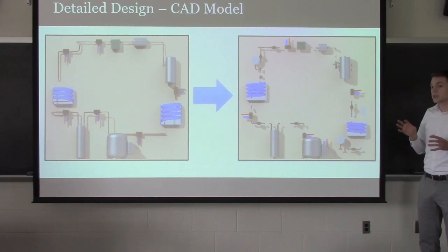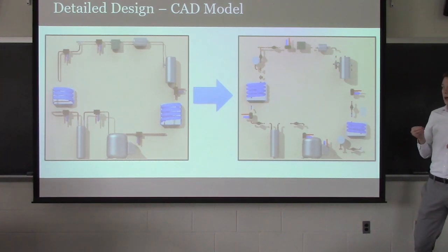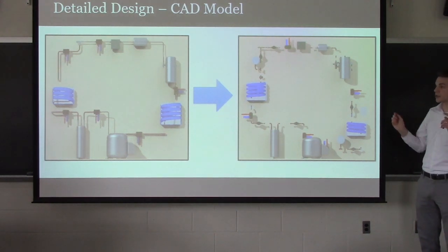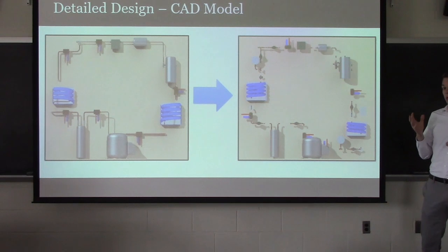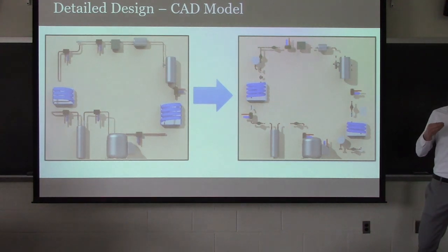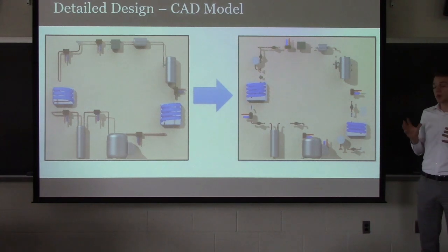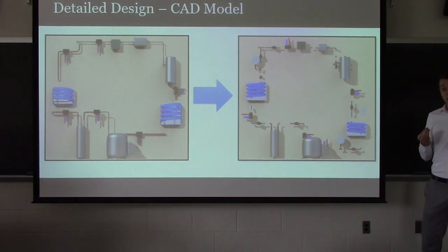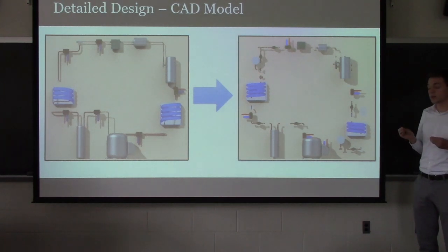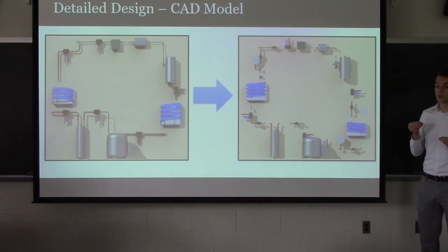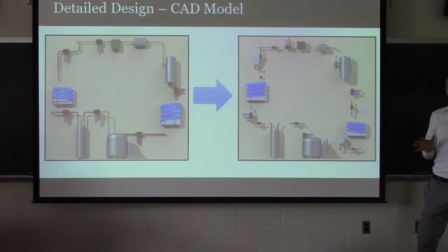Now, major changes here is that we were able to add copper tubing elbows and T's that we're going to need to assemble for soldering, as well as we switched the heat exchangers around, so the one with more coils that would have a higher exchange rate would be on the evaporator side, as well as we adjusted the spacing because some of the components came out larger than we had previously thought. Now, a lot of this, the model we were able to glean dimensions that we were able to use to manufacture the copper tubing that we would need to solder together and finalize the design.